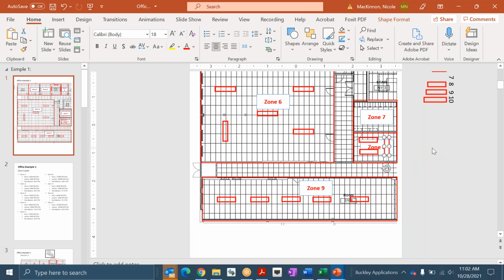In this scenario, if I had a load density that high, I'm actually not going to be able to comfortably fit out that room with 3 8-foot chilled beams. You really don't want to have this many active chilled beams close together. So in some spaces, like a server room, you have too high of a load density, and we actually can't get enough beams in the ceiling to treat that load. So that's a challenge in some spaces.